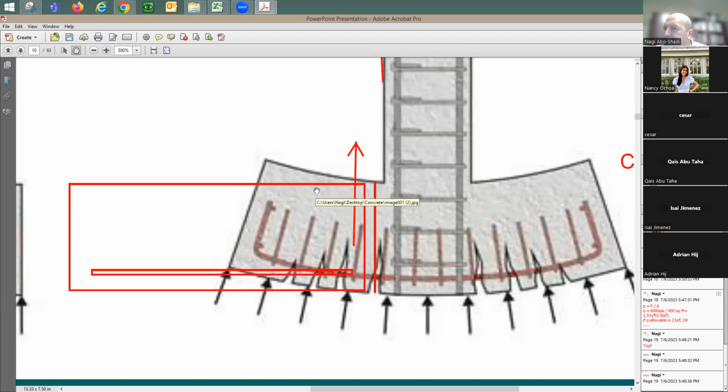Here we're covering concrete design. The reason I'd like to bring in the foundations is so that you understand the application of concrete design when it comes to foundations. At the end it is going to be a concrete section with some bottom reinforcing, and I need to find out how much capacity I have in this section. It can happen in the beam, in the wall design, in the column design, in the footing design. It happens in any structural member made out of concrete. This is the reason we're trying to understand how to size the footing.